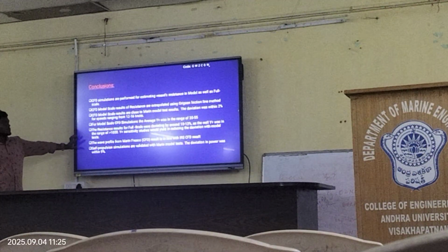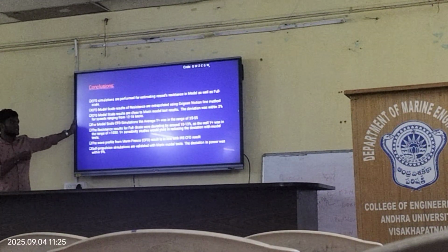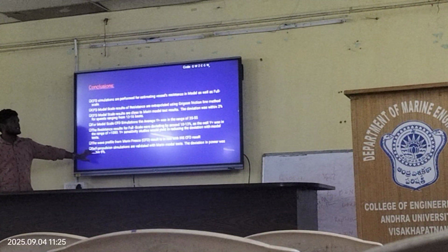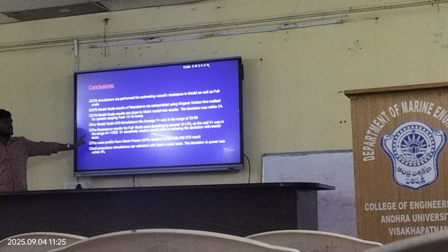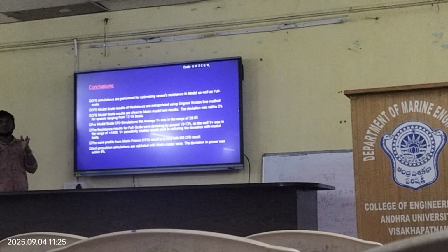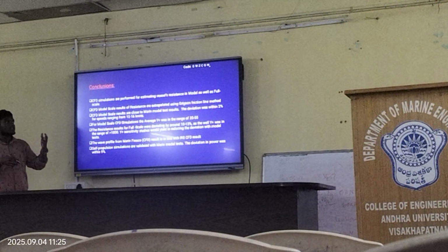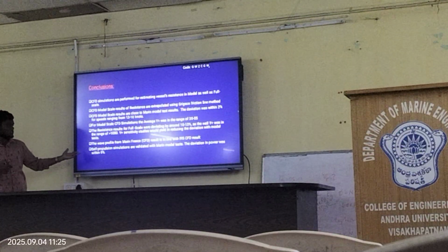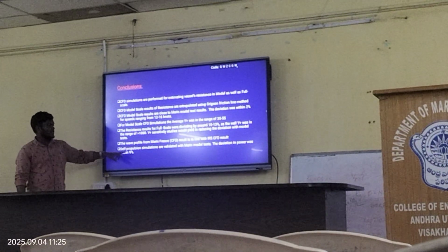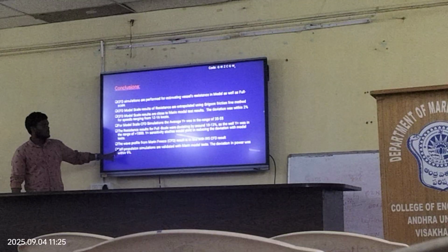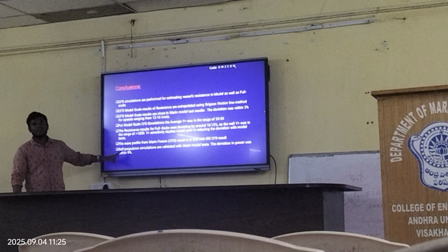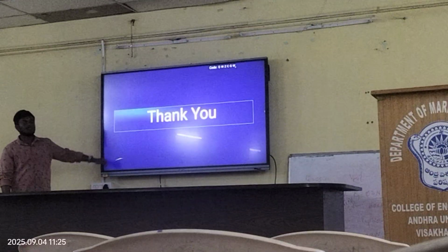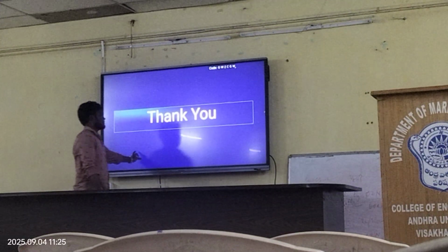I have also done self-propulsion simulations and the deviation in results is 9%, because I have run it for the full scale resistance. Actually, we do the resistance calculation and then keep an actuator disc behind the ship and then run the self-propulsion test. So I have obtained this 9% error, but further refinement of the mesh may yield better results. This is what I have done. Thank you.